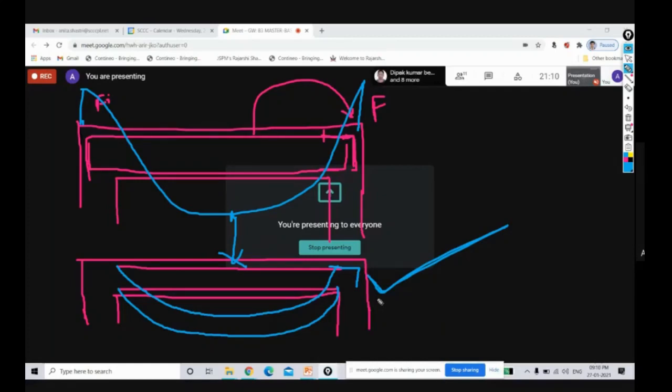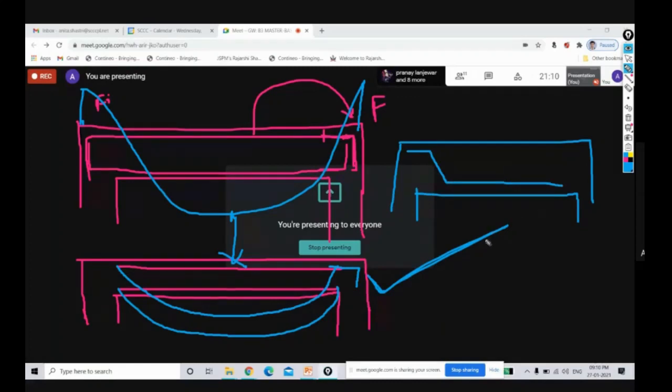One more important thing in slab. Suppose in slab, generally we provide alternate bent up bars, correct? But at the time of casting, so many workers are there. Whatever concept we have used for this bent up bar, that bent should be at the top. But at the time of casting, you see that the reinforcement is not at the top.